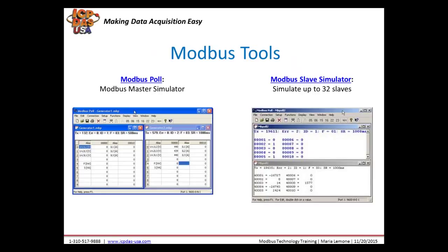It allows you to do things like read the coil status, input status, holding registers, input registers, write to registers, and things like that. Modbus uses registers to hold the data, and you can access the data and turn things on or off, but basically the status of the I/O and the measurement data is all stored in memory registers.